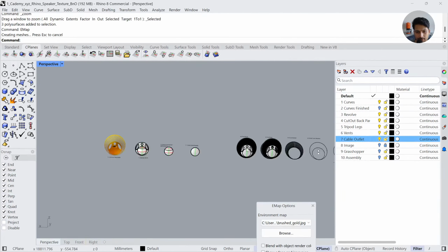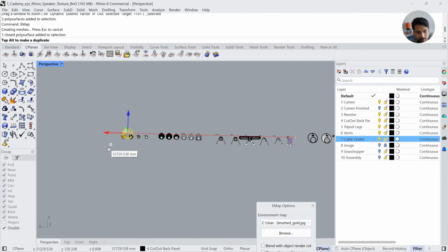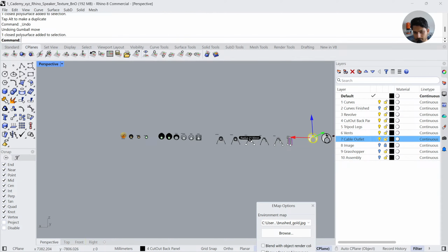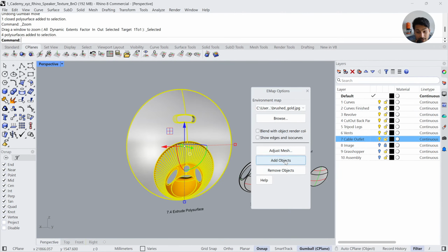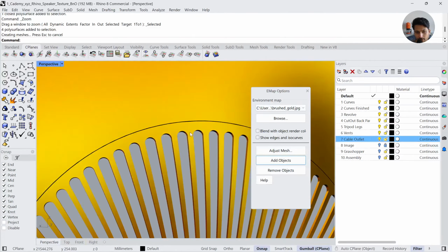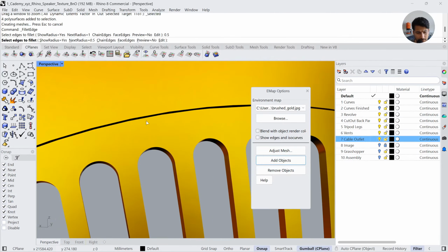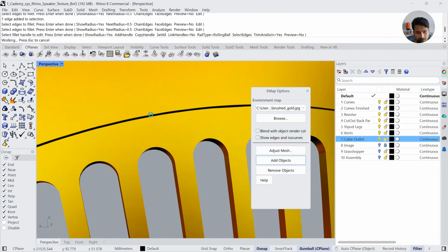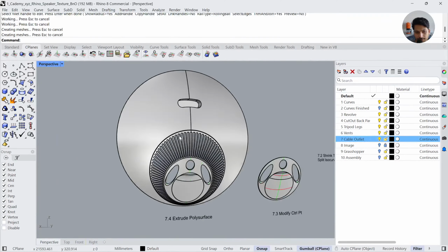And you can also assemble this outer part by moving it with 13,000 units. Okay, this is the advantage of spacing the objects with fixed distance. Now I can align them easily without using any specific command. Lastly, if you want to add micro fillets, you can go to the fillet tool and maybe add a millimeter or 0.5 millimeter fillet on all of these edges. Okay, to create a better visual output.